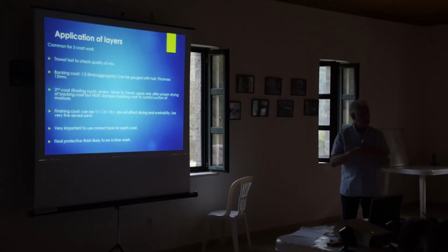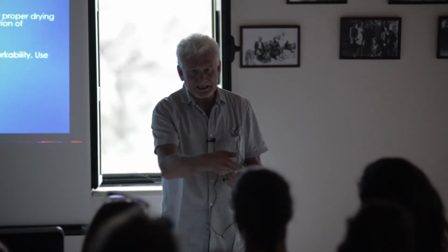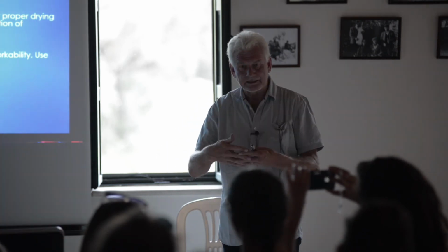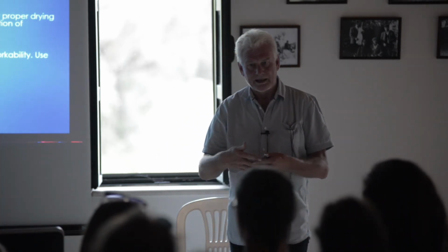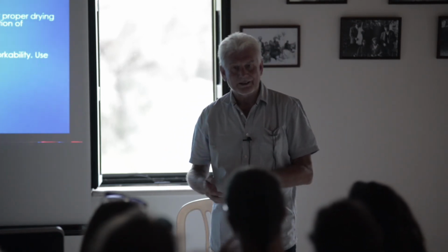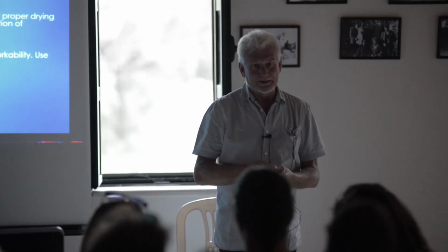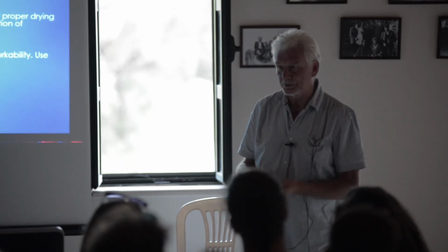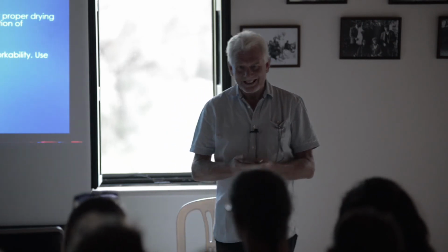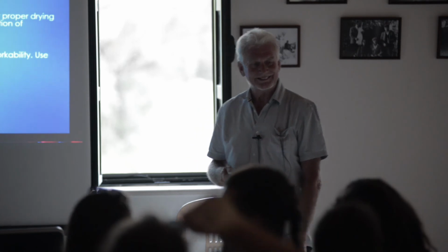The backing coat, the very first coat that you put onto the wall, you can gauge that with hair. You can put hair into the mix, and it helps in binding the render together. It's usually animal hair, goat hair, cow hair, horse hair mostly in the UK. There's those amongst you who have got beautiful hair, and you can use human hair.